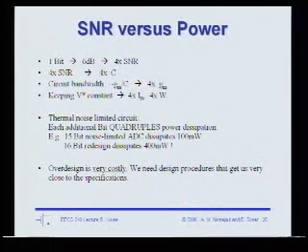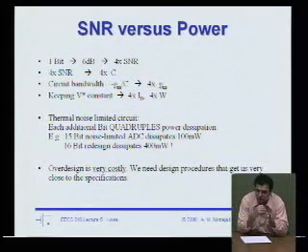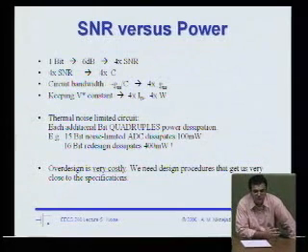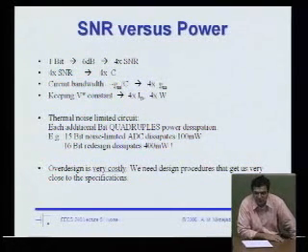Okay, so I think we also talked about this slide as well. One of the issues with analog circuits, just to review very quickly, is that if we want to increase the performance, in other words, increase the number of bits, in other words, increase the SNR, we have to increase the capacitance. And because the bandwidth of the circuit comes out to something like GM over the capacitance, in order to keep the same bandwidth, we have to increase the GM. So to get one extra bit out of an analog circuit, we need to increase the capacitance by 4x, because the SNR is determined by KT over C. That means increasing the GM by 4x.